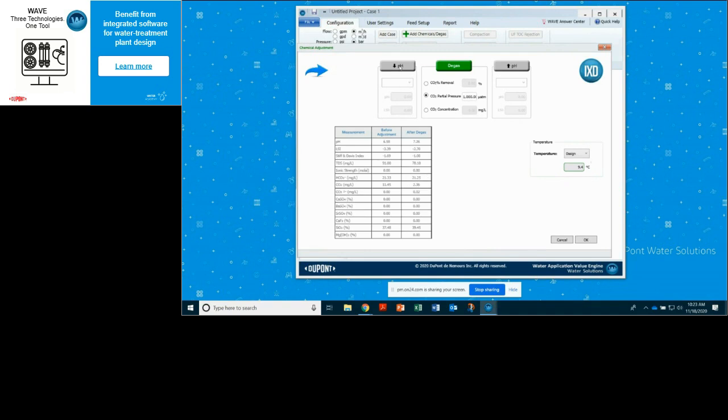Well, you could come up here to our previous button, click on it, and I'm going to add a trace amount of hydrochloric acid. And if I add acid, say to a pH of 5, I drop the pH. I convert almost all of that bicarbonate into CO2 because I lowered the pH, and I now have all that chloride adding to my TDS. As I degasify the system, I actually get rid of a lot of it to the CO2, so now I have a lot less CO2 and bicarbonate left behind.